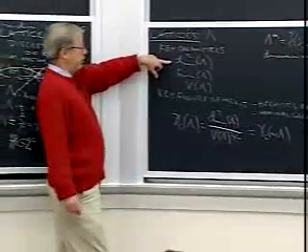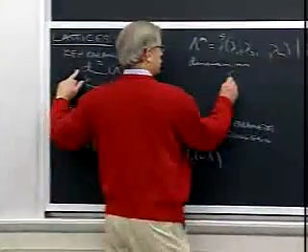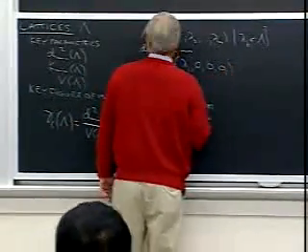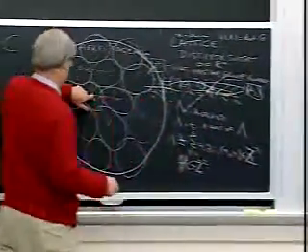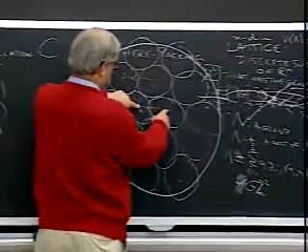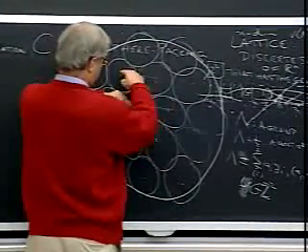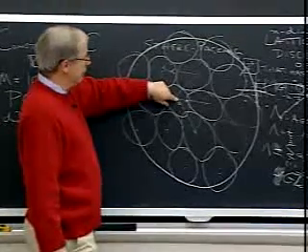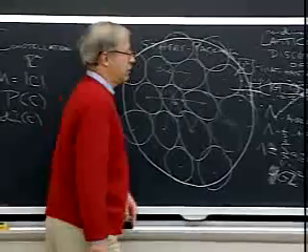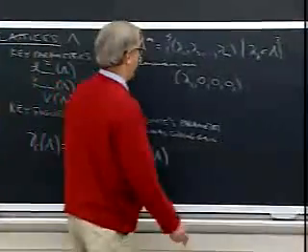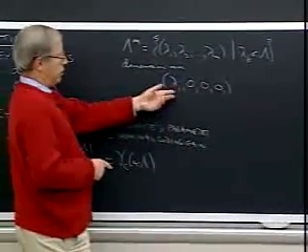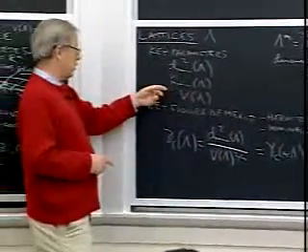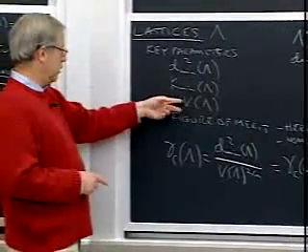Well, what happens to d min squared? D min squared doesn't change because we can always do things relative to 0. D min squared is, by the way, the weight of the smallest, I should have said that. D min squared, therefore, is the squared norm or energy of the lowest squared energy non-zero lattice point, same as we did with Hamming codes, just by the group property. K min is the number of such lowest Euclidean weight points. Okay, here, what's the lowest weight point? It would look something like this, where this is one of the lowest weight points in lambda. So d min squared doesn't change. This changes, but we're not considering that.